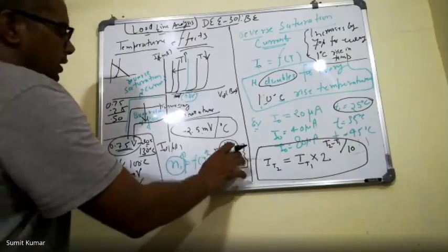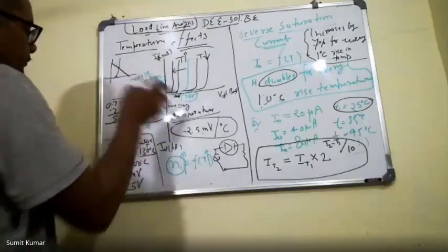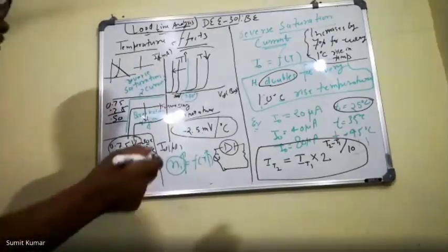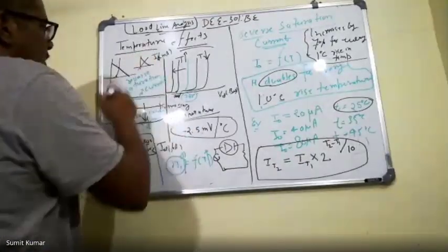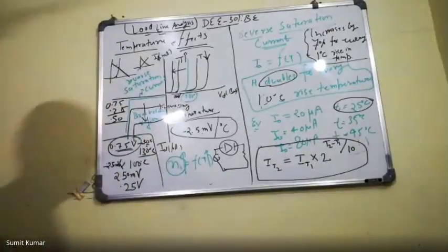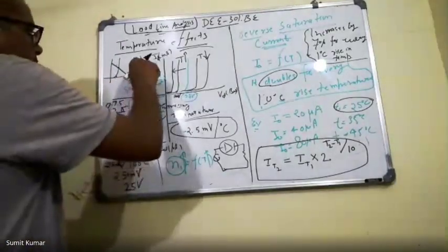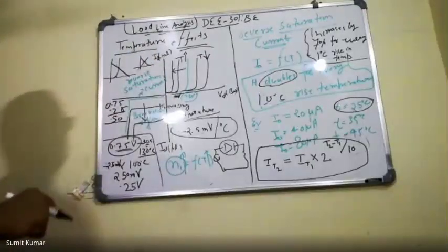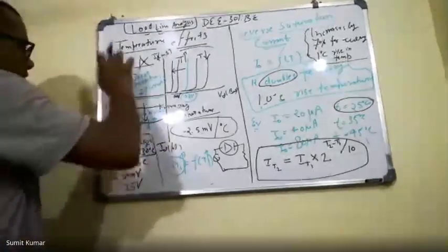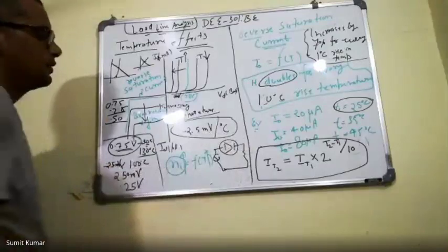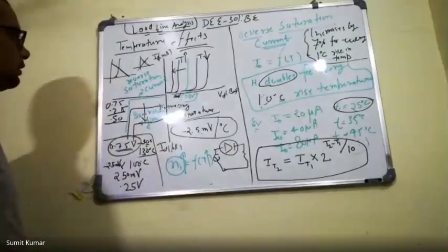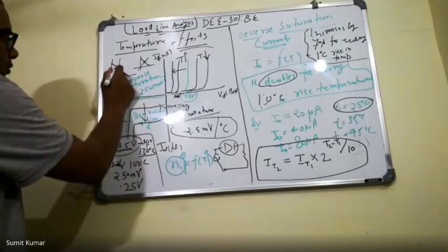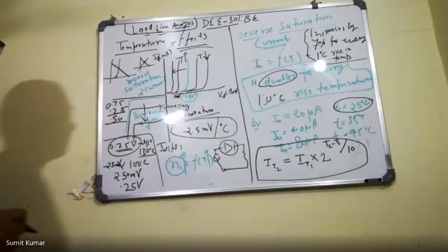With the help of these elements we will try to draw the other line. We learned in the ninth or tenth class that we can find the solutions of linear equations with the help of graphs: we plot them, and the point where they meet is the solution. Similarly, we have a non-ideal characteristic which is known to us, and with the help of other elements we can plot the other characteristic, and the point at which these two curves meet will be the solution for our circuit.